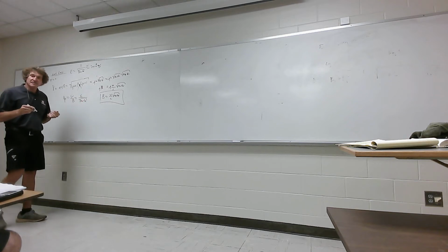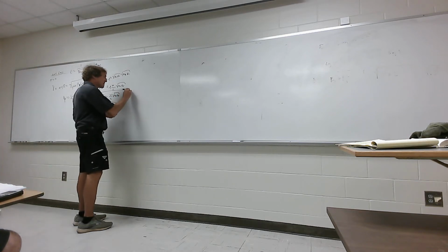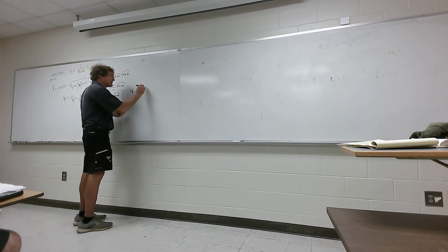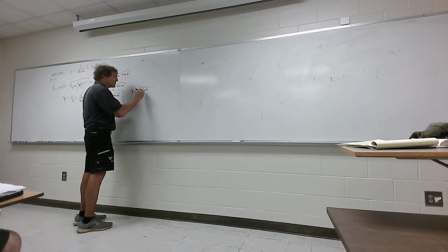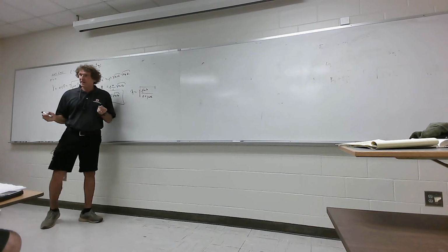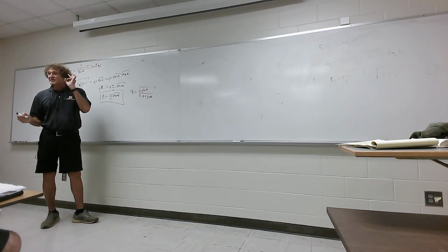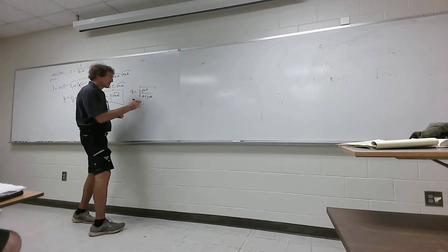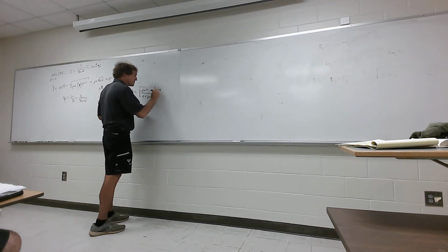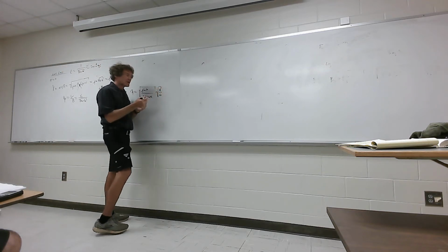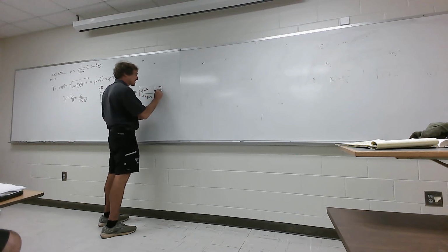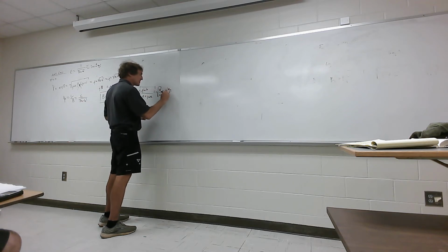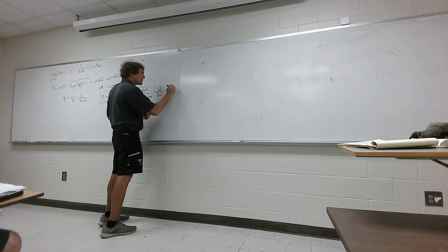One last thing, if it's lossless, if I talk about eta, technically it's the square root of j omega mu over (sigma plus j omega epsilon). Do you all remember that? All right, if sigma is 0, what does this become? That's right, the square root of mu over epsilon, or you can say that's simply the square root of mu naught over epsilon naught times the square root of mu relative over epsilon relative.